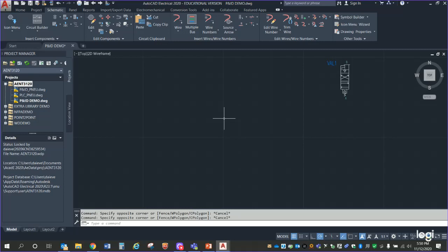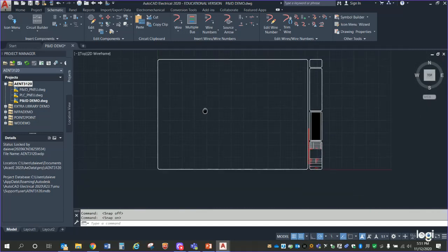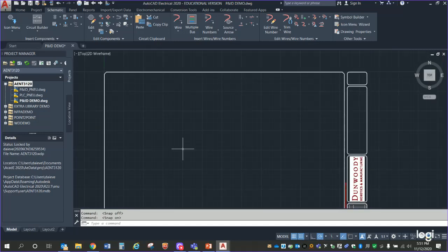We're going to start this circuit very similar to the way we've started any other circuit. And actually, you know what I'm going to do? I'm going to get rid of that guy for right now. I'm going to delete him. You guys should delete him too. And I'm going to make sure that F9 is on. What does F9 do? Snap. This one's kind of critical because the way these components line up to do the piping and the connections, they need to line up right, and you really want snap to be on for this. So make sure your snap is on, which mine is.